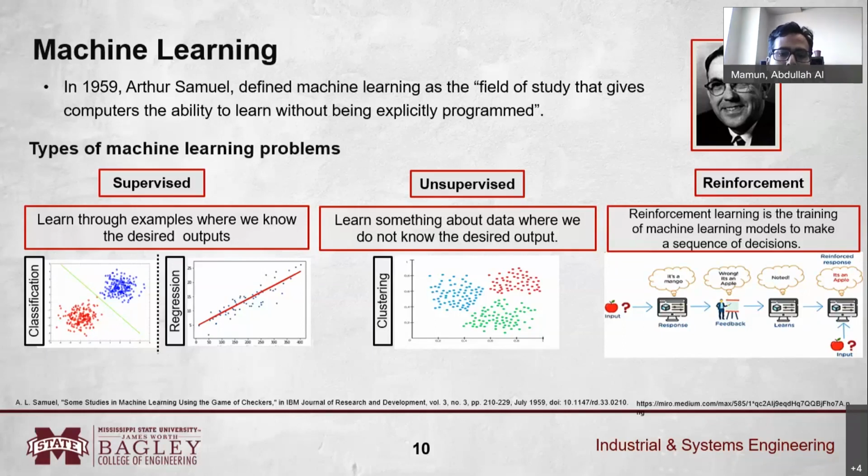In unsupervised learning for machinery diagnosis systems, for example, if you are given a 10-fault bearing data set, we can use k-means clustering and cluster those different faults based on the number of faults we are given, and then classify them in unsupervised learning.